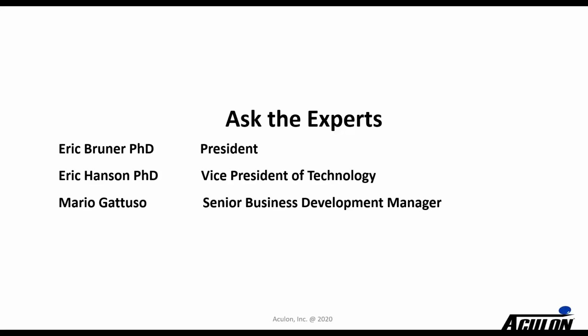Okay. Question for Eric Bruner, do you make pad printable soft coats? That's an interesting question. Yeah, for pad printing, typically you'll need higher viscosity formulations. We have delved into that. One of our nanoproof coatings that has really good oil and water repellency was formulated to be pad printable. So that's something we can explore if there's interest.